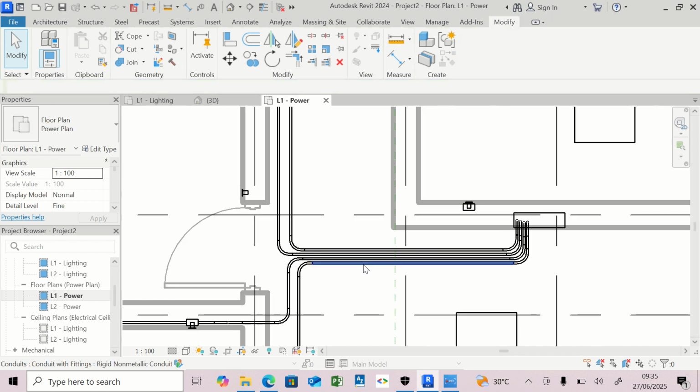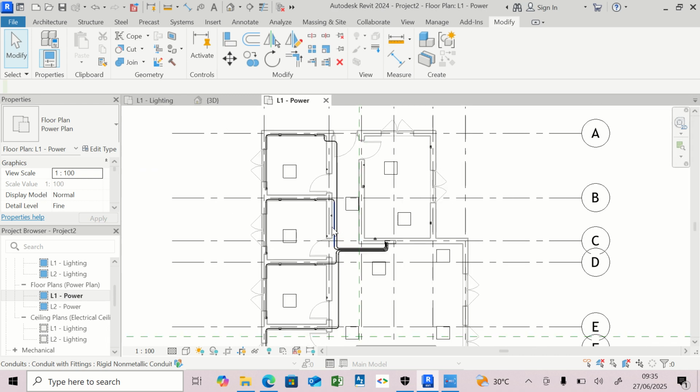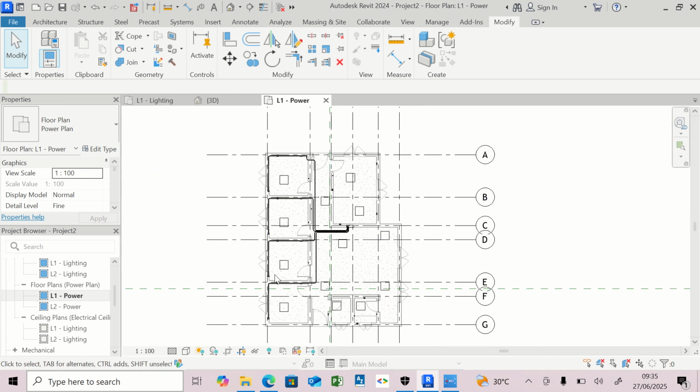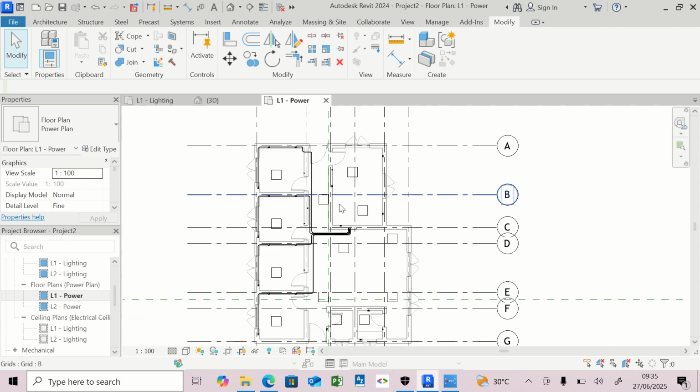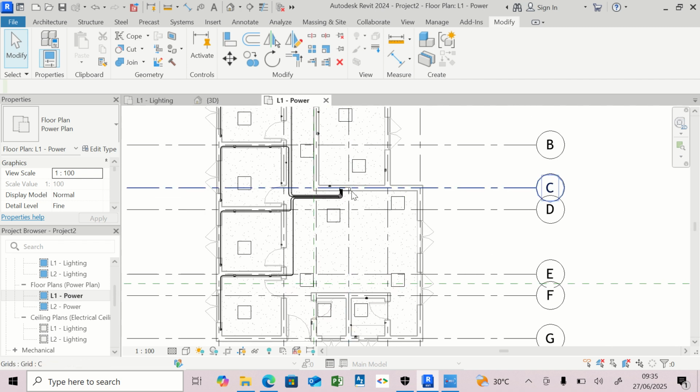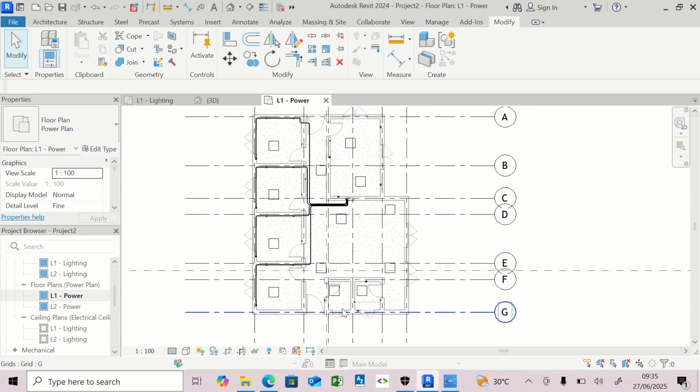So this is great. All right, this is great. So we'll be able to draw for this one. So I'll allow you to do the remaining spaces. So just assume we have one circuit for all the sockets in this office. For the open spaces, we have one circuit for all of them, and they combine with that of the kitchen.